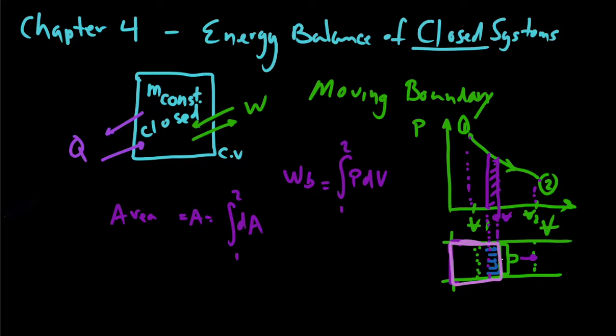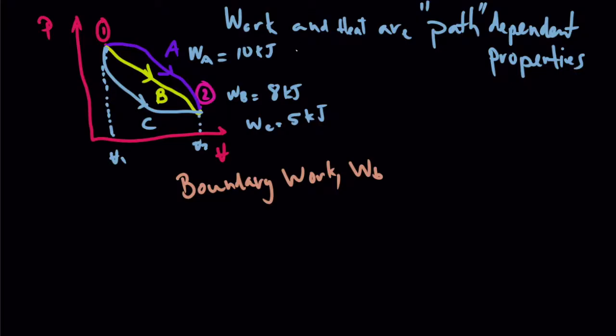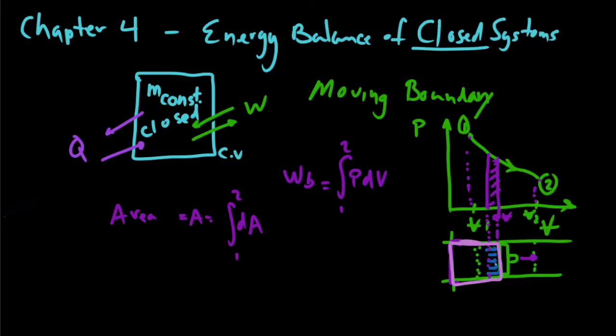So right here, at this position, it is that, and then it'll expand all the way out here, so this volume will stretch and will shrink. It will stretch to a maximum at V2 and shrink to a minimum at V1 and everywhere in between. So this boundary is always stretching and shrinking as the piston oscillates. So it's a moving boundary, and this is what we call boundary work. Going back to that picture, it's basically the work associated with this piston here.